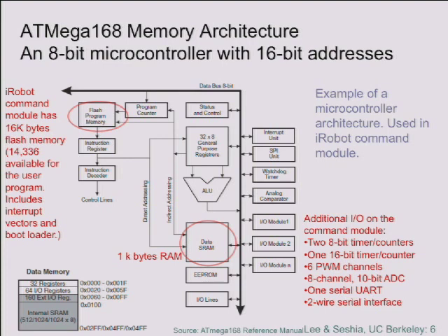The next 160 are also I/O, but I think what it means by external here is that there's no hardware provided on this device for them, but you could hook up hardware to it. And then the remainder is the internal SRAM, and that ranges from this address, which is hex 100, up to some number that is basically 1 kilobyte bigger than that.